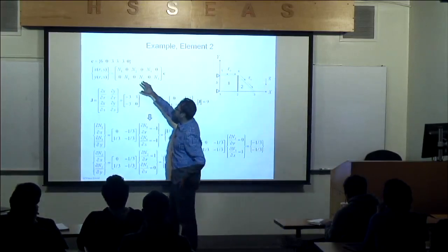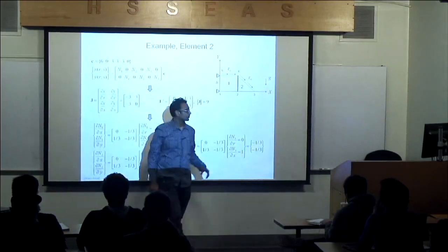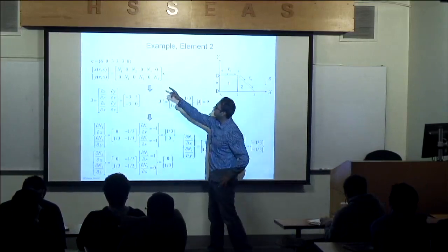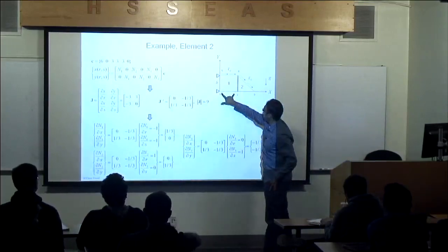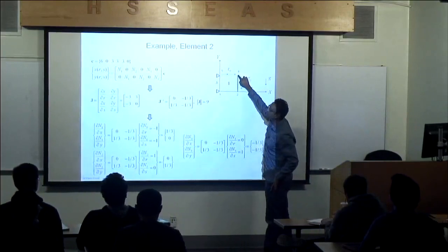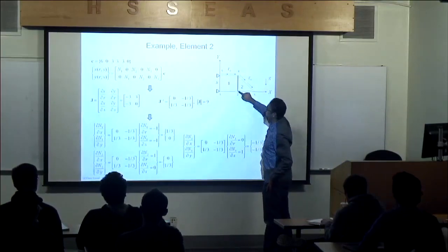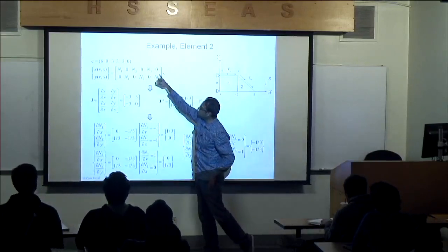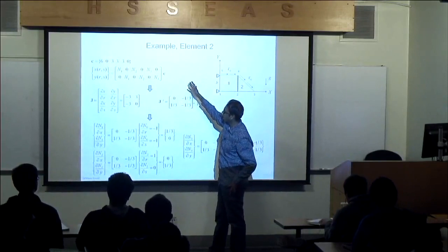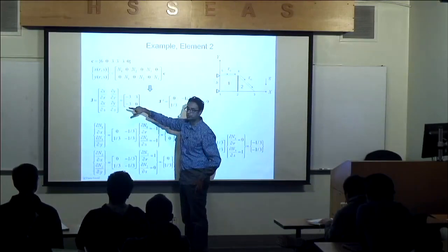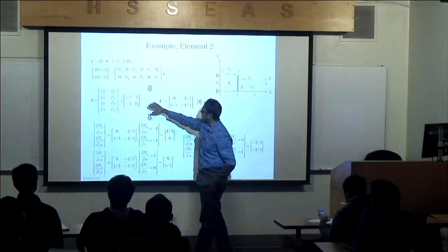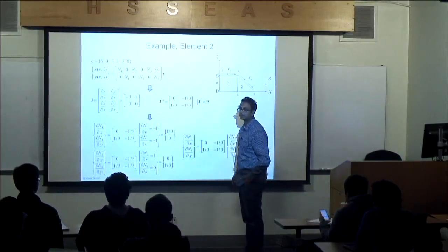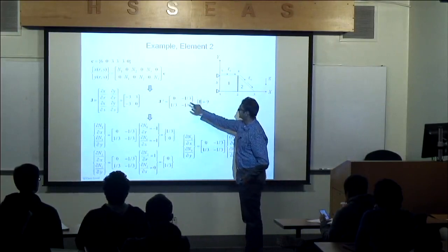So then I have the coordinates of that first node, which is 6, 0. And then second node is here, so this is 3, 3, that location. And then 3, 0, which is this node here, third node. Okay, so that's the coordinates there. Shape functions times that gives me what I need to then calculate the Jacobian. And when you do that, you get that, J inverse is just that. I had to do it with Mathematica. But the determinant is 9.